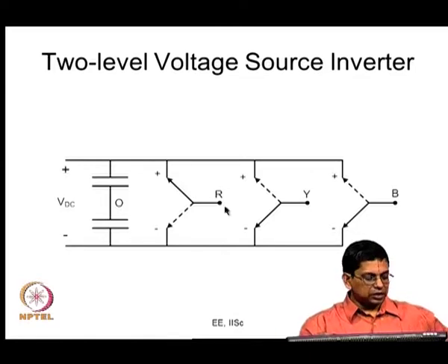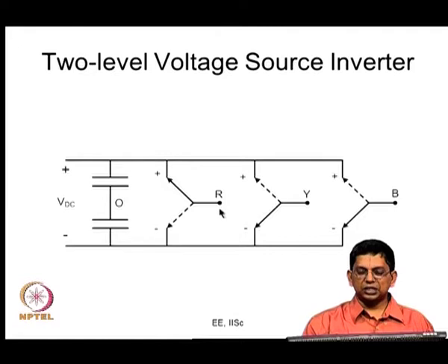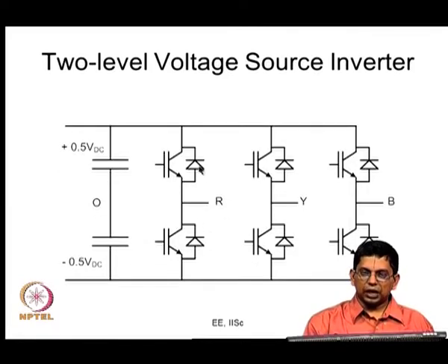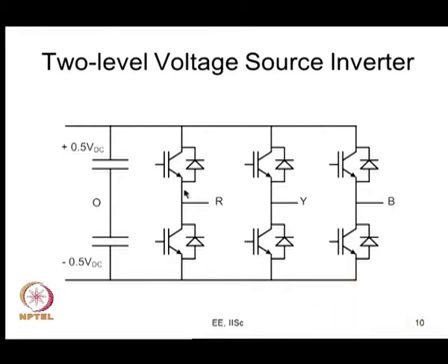One thing that we realized here was this is for DC AC conversion, where you use single pole double throw switches in a 3 level. And this is how they are actually electronically realized. You have 2 transistors, and each transistor has an anti-parallel diode. It can conduct in both the directions, and it can block voltage with a particular polarity.